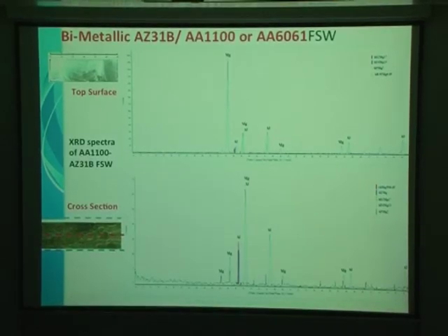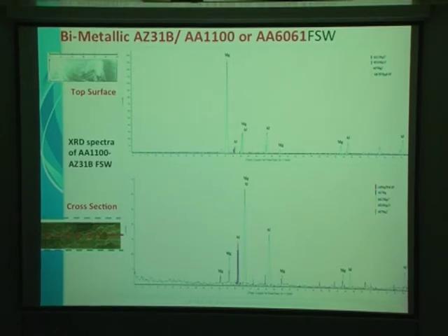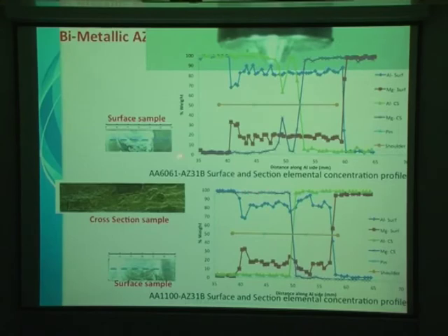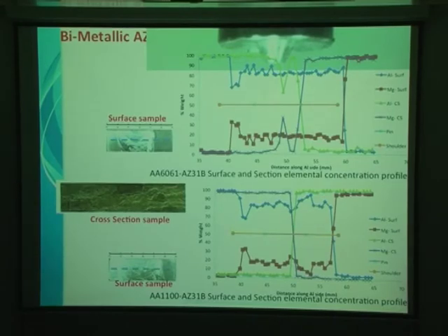and you look for the alpha, beta and gamma structures, Al12Mg17. You look at the distribution of what's happening. Is the magnesium going into the aluminum or not? Those measurements were from EDX, energy dispersive X-ray spectroscopy. The analysis shows that there's a lot of mixing from the aluminum to the magnesium and so on and so forth.